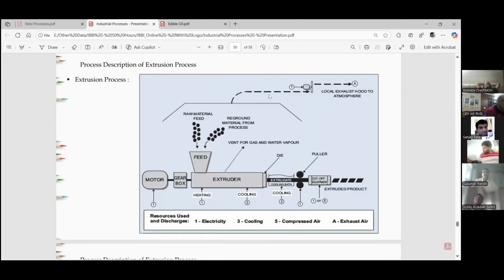If any plastic article is long in size, just like a plastic pipe for gardening or a PVC pipe, that cannot be produced by the injection molding machine. It is produced by the extrusion machine or extrusion process, the plastic extrusion process. So the concept is the same. We feed the plastic granules in the form of HDPE or LDPE through the hopper to the barrel. Okay. Again, due to the heating, your plastic granules are converted into molten plastic.